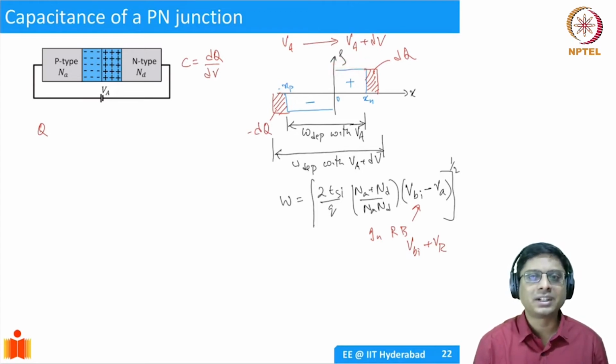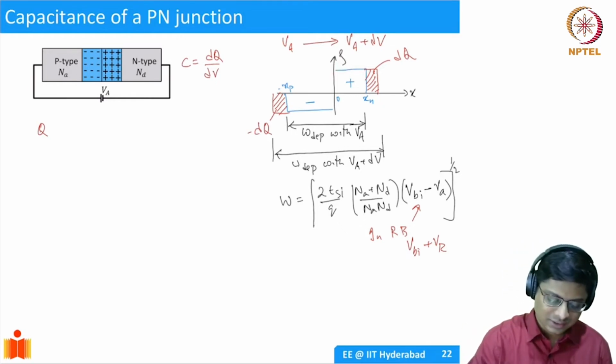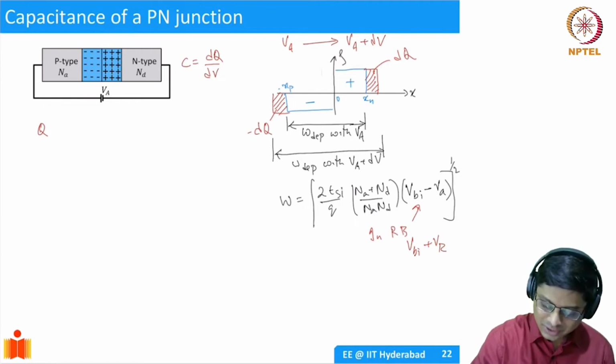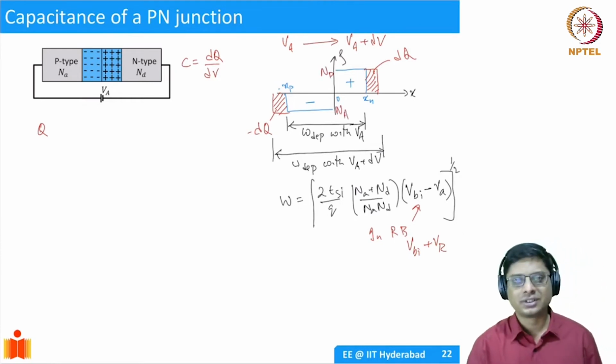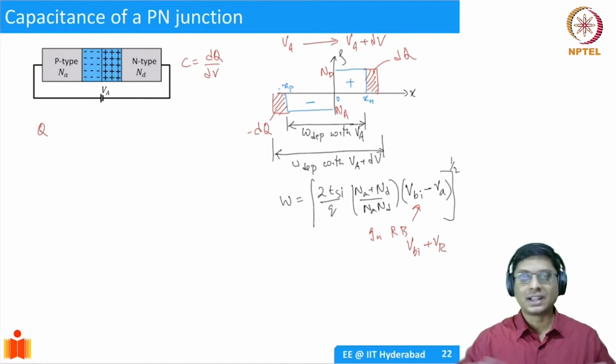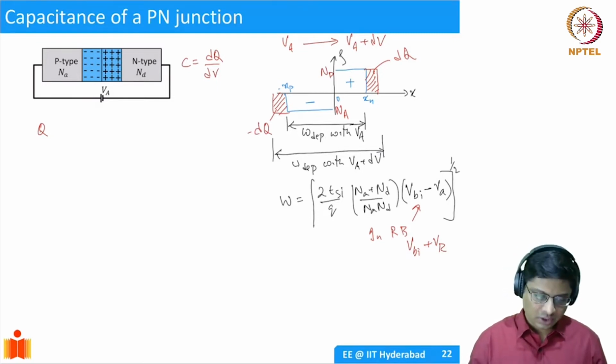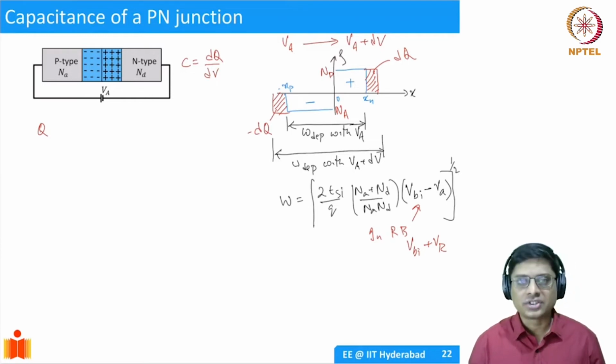I mean, it should be very clear by now that it's uniform doping. So you can't change the y-axis. This is going to be determined by your Nd, and this is going to be determined by Na. That cannot change. That's the lattice fixed charge. We can only change the extent to which you remove the electrons or holes. So on the x direction, you can change. Okay. All right. Let's come back to the charge.